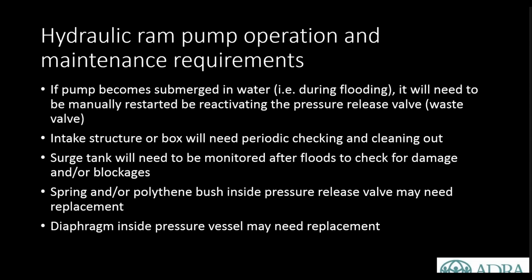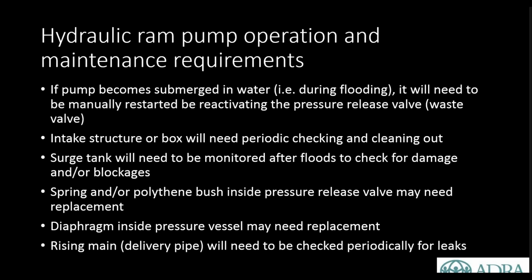And there's also a diaphragm inside the pressure vessel which may need replacement. We haven't actually had to do that. We've had no issues with the springs or the polythene bushes or the diaphragm inside the pressure vessel, but they are moving parts, and as such they may need to be replaced at some stage. The rising main or the delivery pipe needs to be checked periodically for leaks.